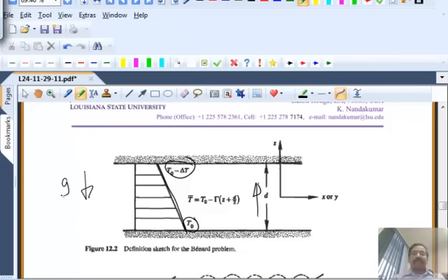Just like in the previous case where a faster moving inner fluid element gets thrown out by centrifugal force, here what happens? A fluid element that's at a lower level at a higher temperature becomes lighter and wants to rise up. Okay? That is the destabilizing mechanism that causes these convection currents, going up and coming down.